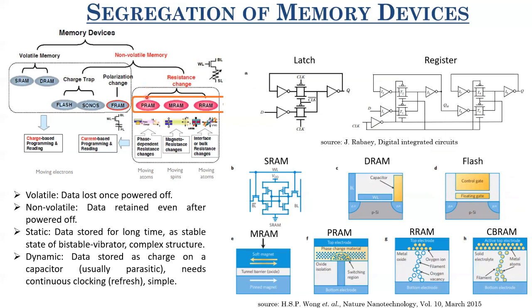So the first memory there is PRAM, or phase change memory as we call it. So what is a phase change memory? Essentially, it is a 2-terminal device. So these were 3-terminal devices since they are MOSFETs. All these memories which I talk about here, they are 2-terminal devices, right? Here you have a top electrode and a bottom electrode, and then there is this phase change material over here. And at the bottom, there is an insulator. But what you essentially do is you fabricate a protrusion of metal, the bottom electrode, which goes to this phase change material.